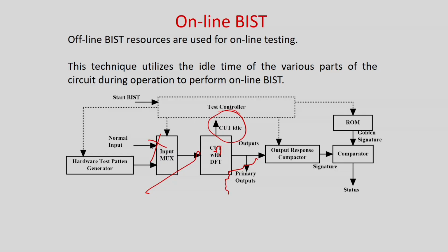Standard BIST. Online BIST is the same as offline BIST, but you just have to find out whether the circuit is idle for some amount of time. Whenever it is idle, you just stop the normal input and do the BIST. That is basically online BIST.